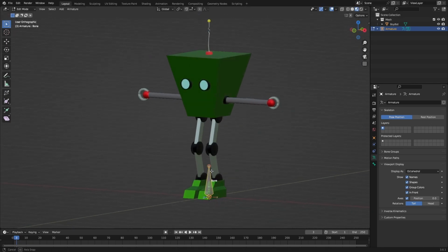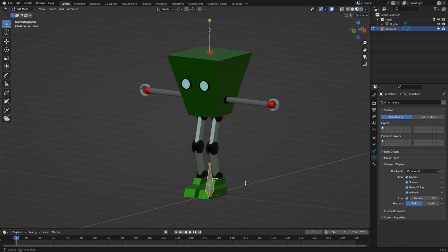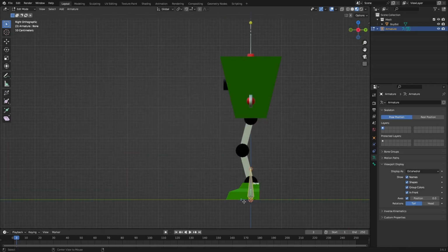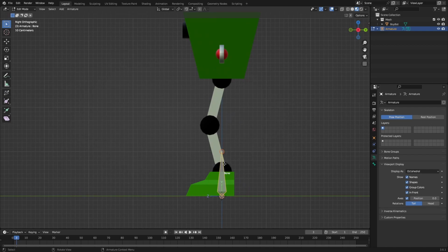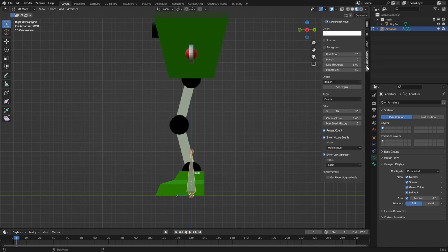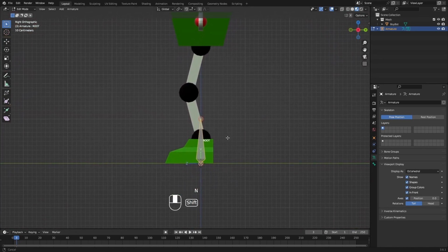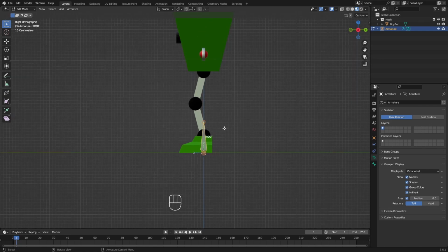One thing that I like to do when beginning a rig is to keep the first bone and name it root. So pressing F2, and one thing that I can't forget here, because it's going to be very important, is to show you what keys I'm pressing. All right, so F2 to rename, and then keep it at root.